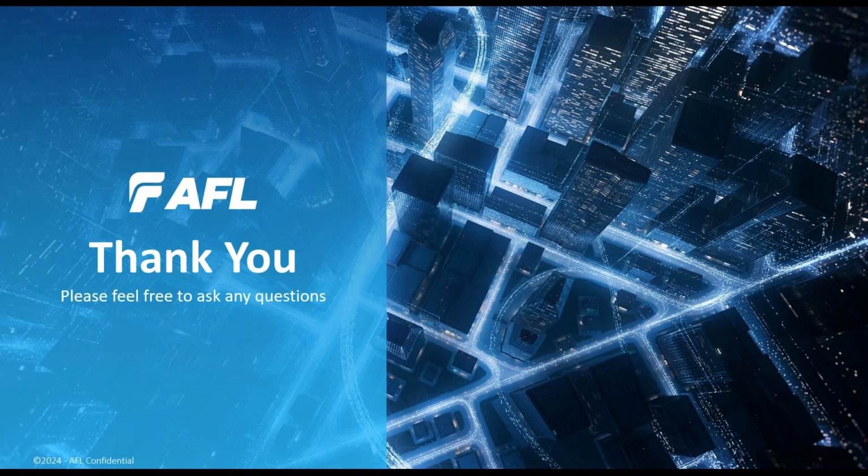Next question. Great. Next one, does any AFL OTDR have a helix factor variable that we can input before testing? Today, we do not include a helix factor variable. You can use the IOR to really compensate for the helix factor.